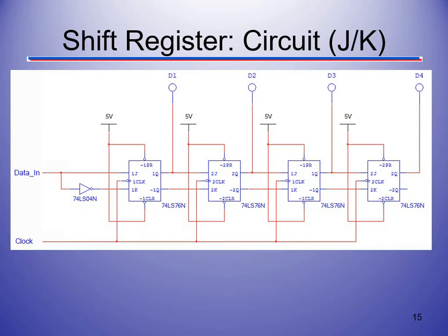Here is what it looks like if we have a JK flip-flop. What are we really doing? For us to shift this data in, J is going to be driven with Q, and K is going to be driven with Q bar, so we invert K originally. Our data might come in as 0, 1. Remember what 0, 1 did with our JK: it's not the toggle command, but it would send the high in, so it's going to lock that.